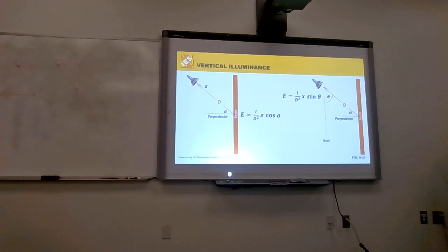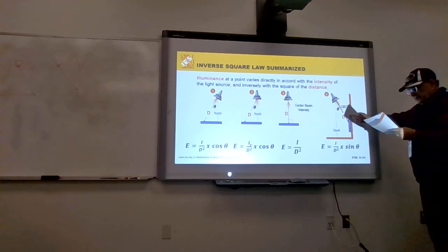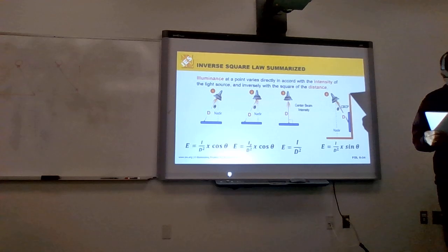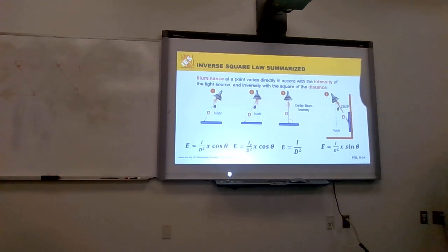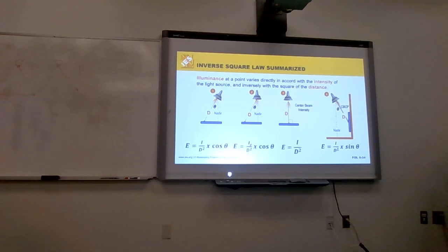So that's trigonometry. Scary, isn't it? Third function, this guy right here. Solve for foot candles when the candle power is 6,000, the distance is 10 feet, and the angle is 30 degrees. Now we need to use the sine of 30 degrees.